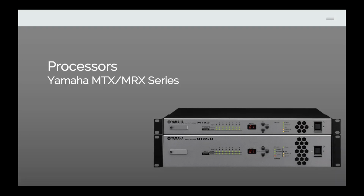What I would certainly say is with any of the MTX or MRX series processors, please do not just take one out and install it, because they don't work out of the box without you configuring them using the MTX MRX software. And there are 8 parameters per input that you need to set, which once you understand are very, very straightforward to do. But if you haven't had any training at all on MTX or MRX series, you're going to be a little bit in the dark.